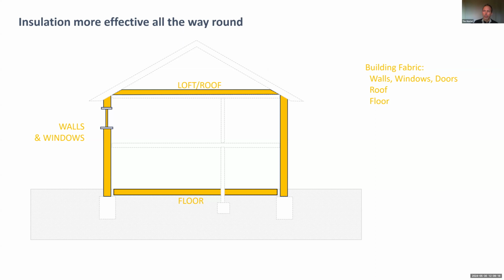and apart from that, you would have to consider the thermal bridges in the floor, and there's more at the wall-to-floor junction there. That's because I'm not showing the wall structure here because I've simplified the diagram, but where the wall structure meets the foundation, that's where you'd have a thermal bridge, and also at the eaves here, and also at the window head and sill as well. So building fabric, I'm including windows in there as well as thermal bridges.